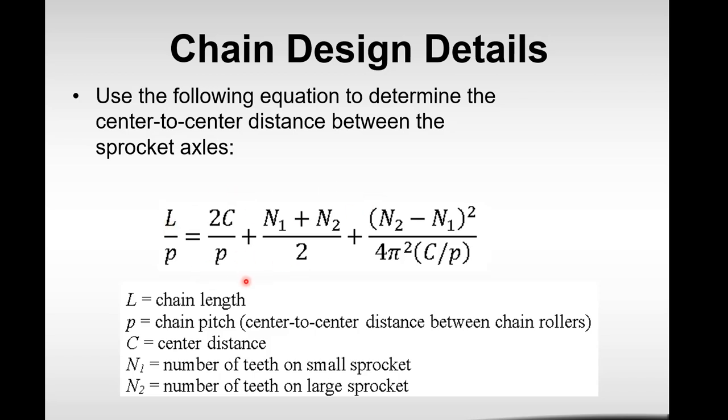But anyway, this equation you can set up in an equation solver. Notice that if you have the C, you can just put the C values in and calculate L. If you have the L and you want to calculate C, then you have C in the numerator here and the denominator here, so it's a little bit trickier. You can set up a quadratic equation and solve for C with the quadratic formula, or just use an equation solver, something probably on your calculator or in MathCAD.